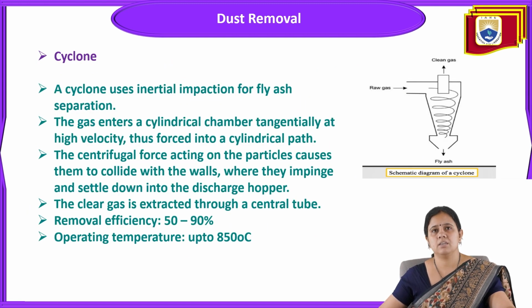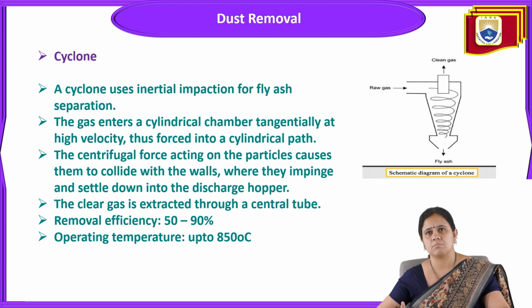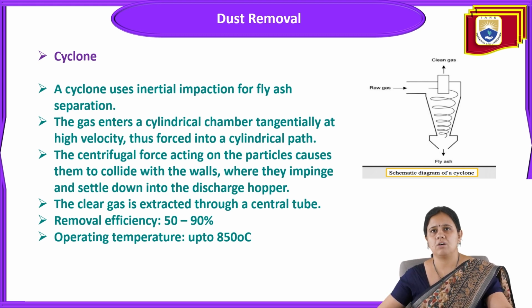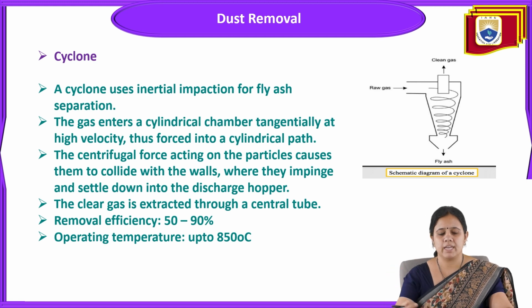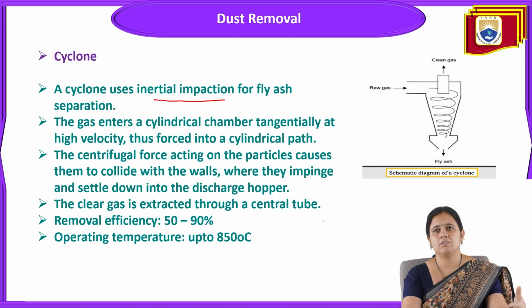Next are some devices used for dust removal. For removing dust from the flue gas, the cyclone precipitator is used. The cyclone works on the inertial impaction principle of fly ash separation.